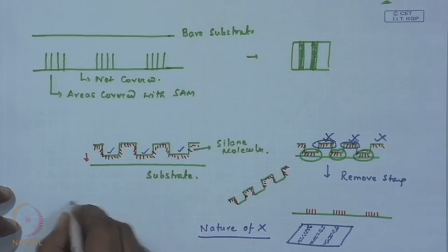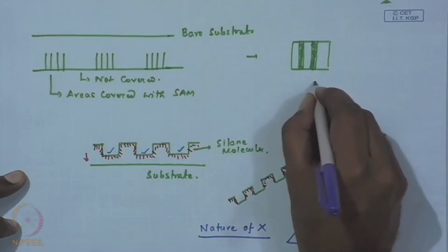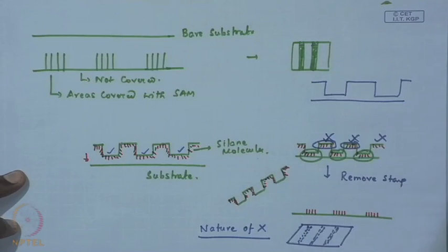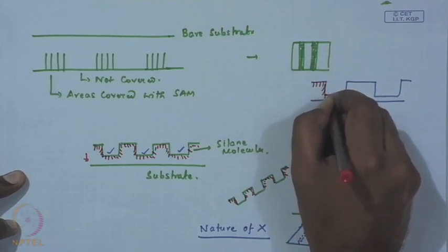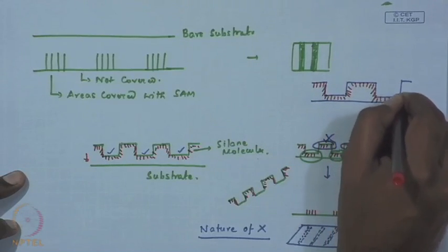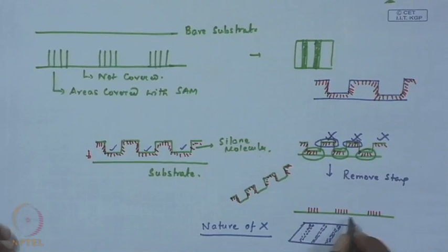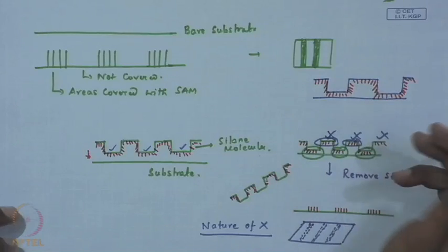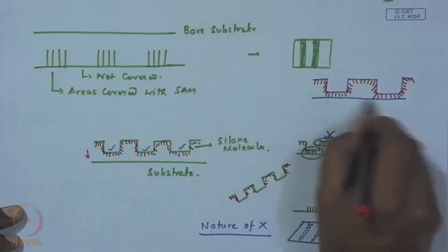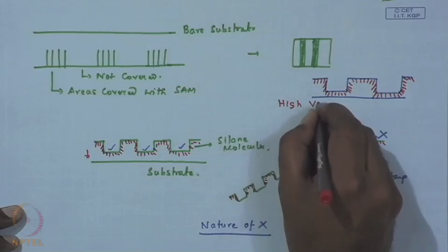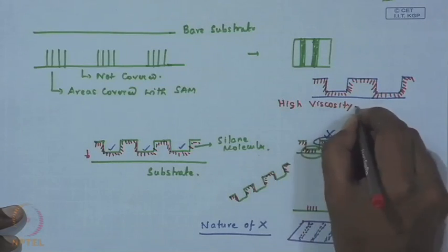Of course, there are critical issues. Let me just draw a quick detail. The viscosity of the silane solution is extremely important, because though it is the preferential attachment that eventually guides the self assembly of these molecules onto the surface, one has to understand that if this wetting layer is too dry or the viscosity is too high, then even during contact, this molecule might fail to transfer from the stamp to the surface.